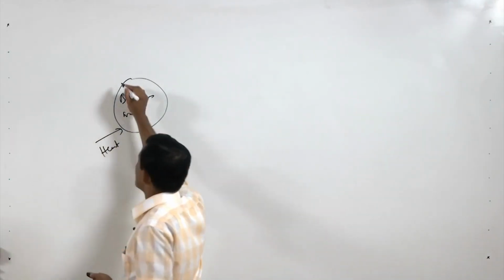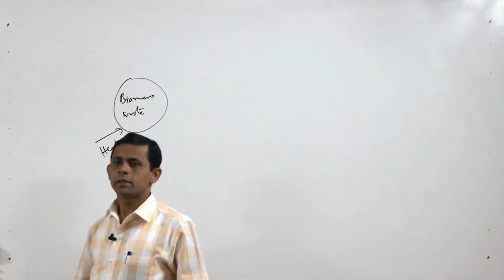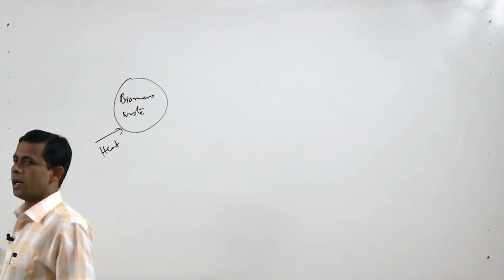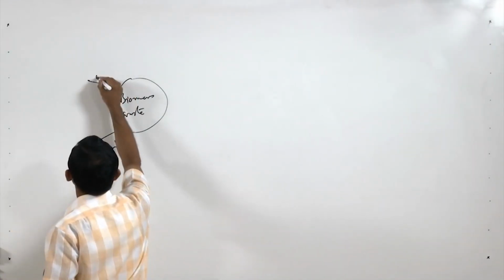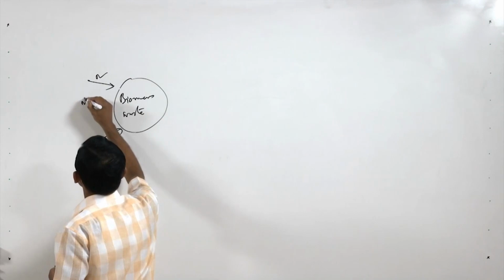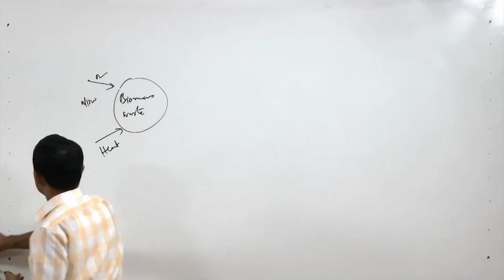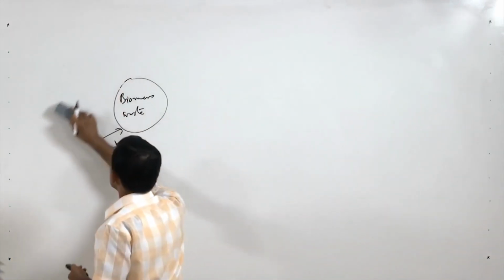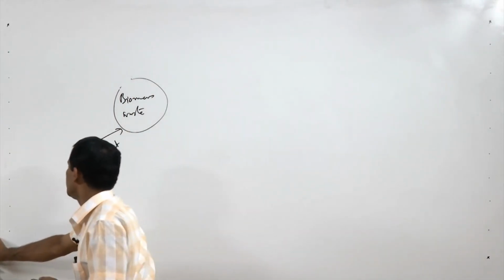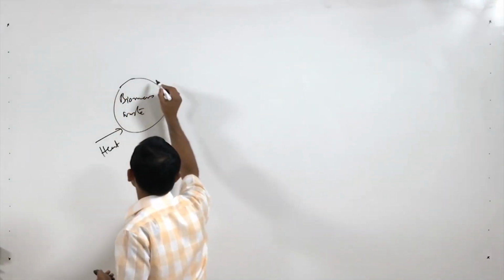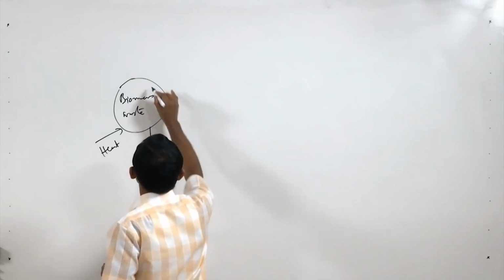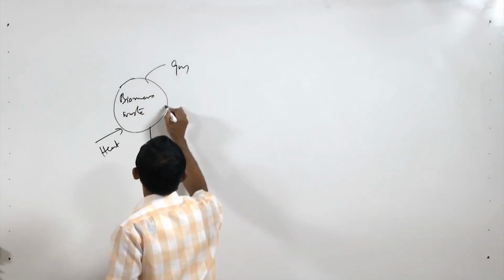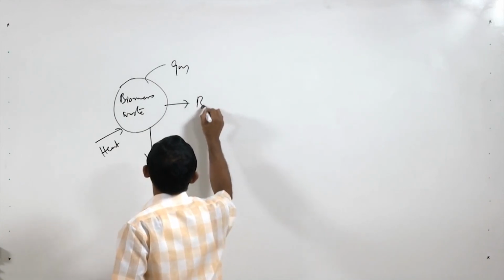In combustion and gasification, we had to put in some other medium, that is oxygen for combustion and O2 and H2O in the case of gasification, but in this case we do not need these two, only heat, and that heat will give us char, gas and bio-oil.